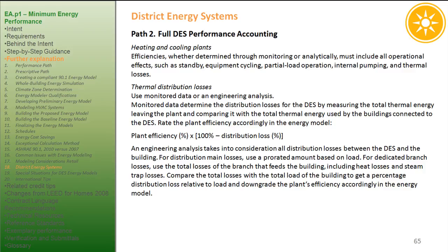Heating and cooling plants. Efficiencies, whether determined through monitoring or analytically, must include all operational effects, such as standby, equipment cycling, partial load operation, internal pumping, and thermal losses. Thermal distribution losses. Use monitored data or an engineering analysis.